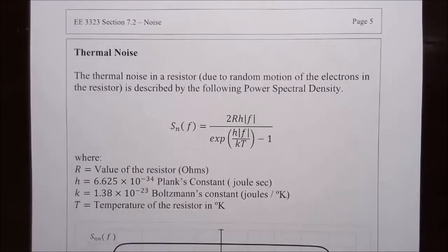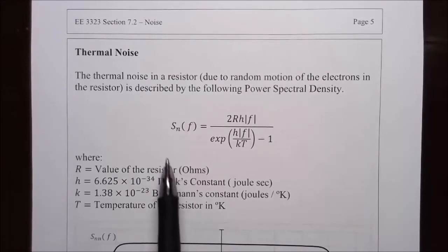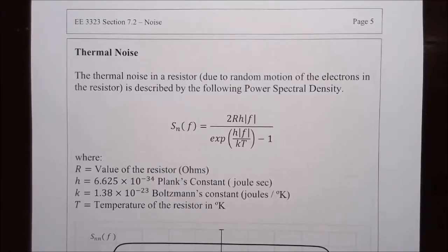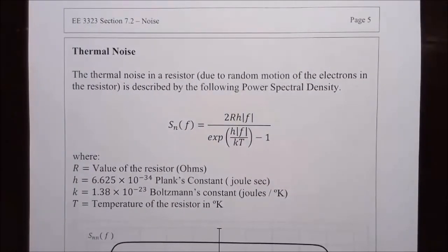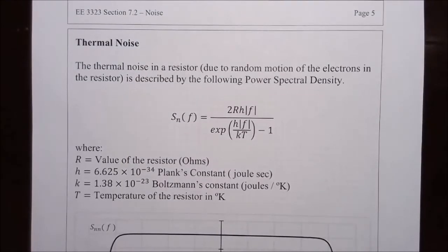Just to back up the idea that this is a reasonable model for noise, I'd like to look briefly at what is called thermal noise. If you pass a current through a resistor, even if you intended to pass a constant current through the resistor, if you were to measure the voltage across the resistor, you would not see, on an oscilloscope, simply a straight line in time. You would see fuzz on the line. It would be a fuzzy line. Now, there's a good question: is that noise coming from the voltage fluctuations across the resistor, or is that noise coming from some kind of noise source inside the oscilloscope itself? That's a good question to answer. But either way, the line on the oscilloscope will not be perfectly straight.